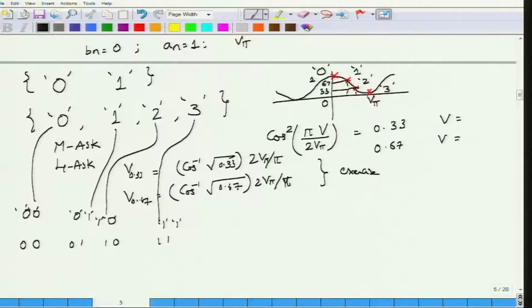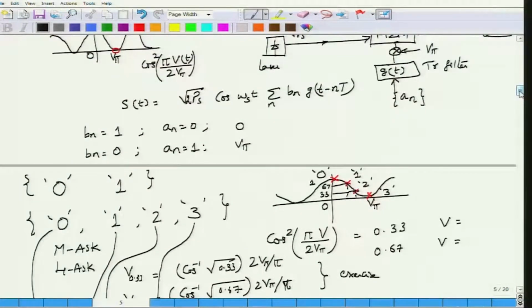In optical communications, finding more than 4 levels of amplitude shift keying is kind of difficult, because the symbols start to group very close to each other, and when symbols are very close to each other, after they have transmitted through the channel, to separate them out and detect them correctly is a big headache. We are going to talk about receiver headaches later on, but you can take it from this one that practically getting more than 4 ASK is quite difficult unless you are very rich to invest in very high end products for optical communication links.